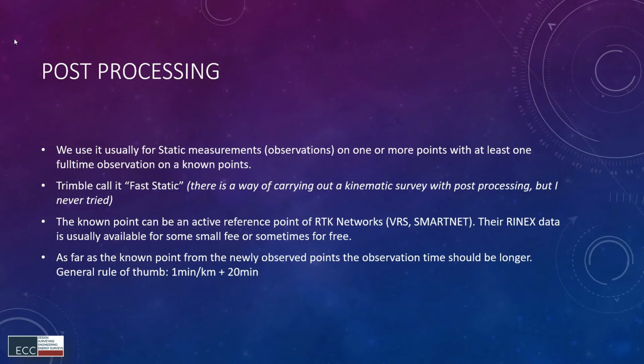Or the other thing is you have to make sure your geometry DOP, GDOP, is quite good, at least under 4, but preferably under 3. It's probably never going to be 1 or something like that, but 2 point something or 3 is alright. And so you have good satellite coverage.